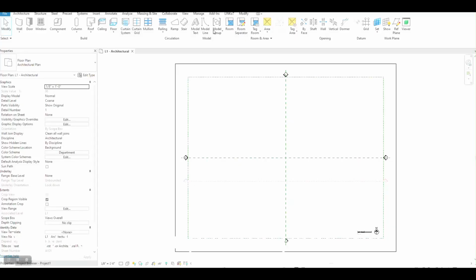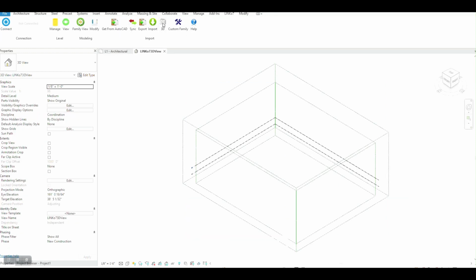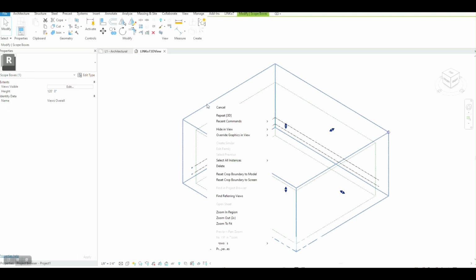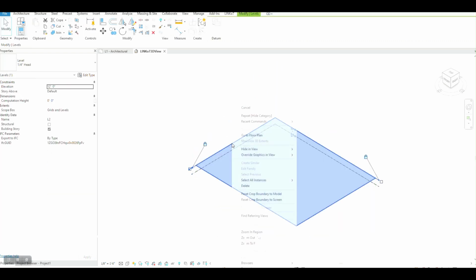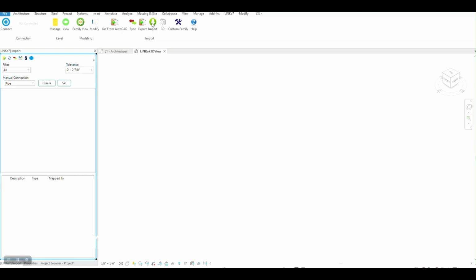Now you can import the plant model in REVIT. Create a new REVIT project. In 2024, REVIT has a multidiscipline template. In earlier versions, you need to choose a mechanical template. To create the plant model in REVIT, click on the Import button from the ribbon.